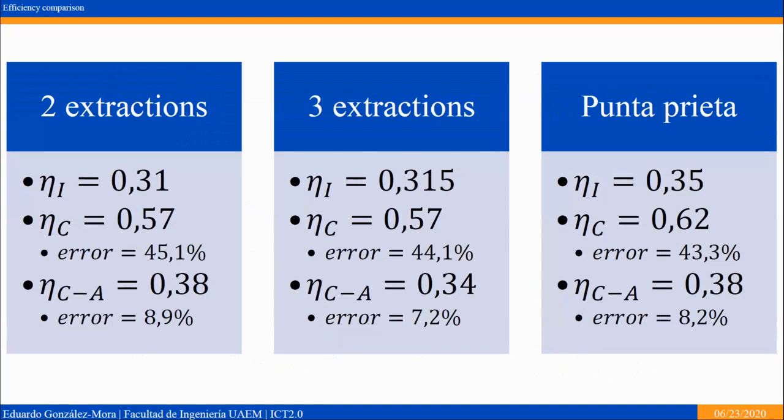Now let's compare the efficiency of the conceptual power plant with the Agua Prieta power plant in Mexico too. We can say that the estimated and observed efficiencies are fairly similar, and so is the relative error with the Carnot efficiency and the Curzon-Ahlborn efficiency. It can be seen that the Curzon-Ahlborn presents a more realistic upper limit, not only for conventional power plants, but also for the solar power plant discussed here.